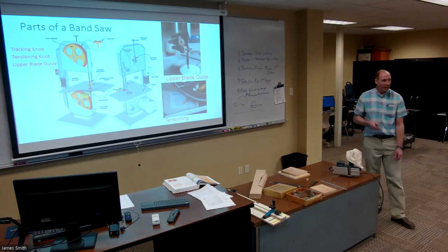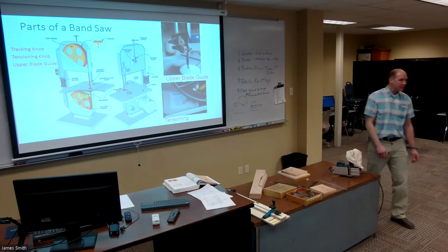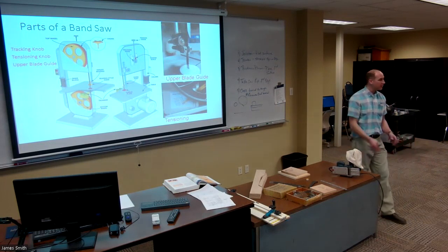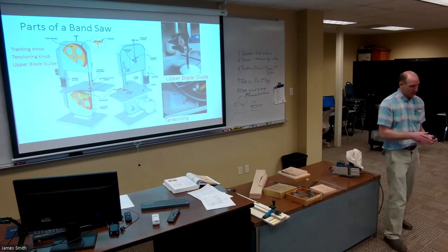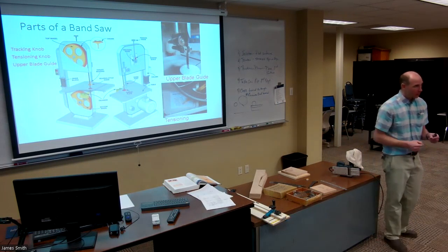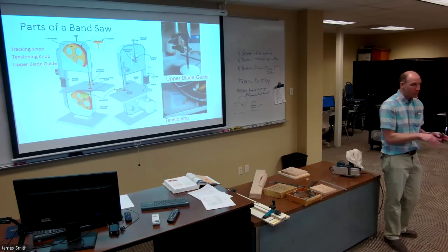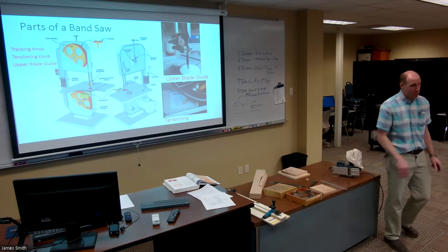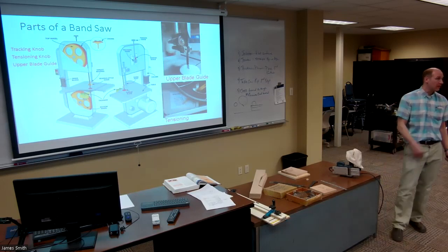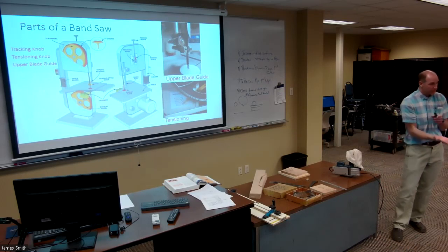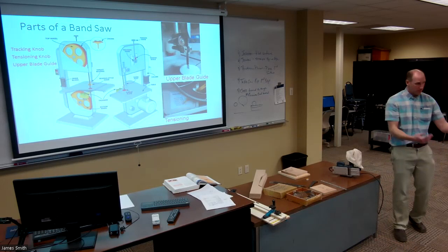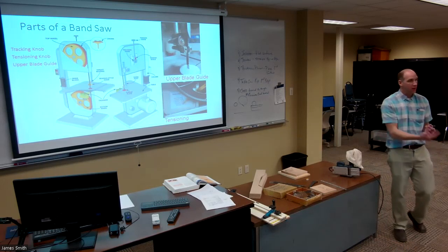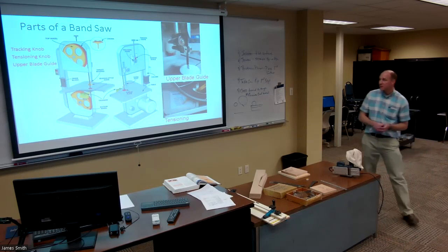We use ours for cutting curves mainly. When I was teaching middle school, I loved our bandsaw. I bought one that you could run a miter gauge in, and it also came with a rip fence. We were using that for ripping boards and cross-cutting boards, and it was great because on the bandsaw there's no risk of kickback. The blade cuts through the wood in a straight down direction. You've got your table underneath, so there's no forward motion that's going to cause it to kick back, and so it's perfectly safe for kids.